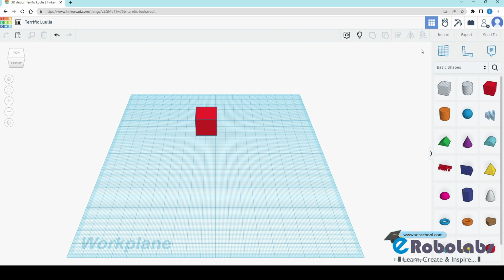And you can find show all in the top right toolbar in the TinkerCAD screen. You see here, it is represented by a light bulb icon. When the show all bulb icon is active in the toolbar, it indicates that your design contains some hidden objects. You can also use the keyboard shortcut Ctrl plus Shift plus H. Just click the light bulb icon and your object is unhidden.